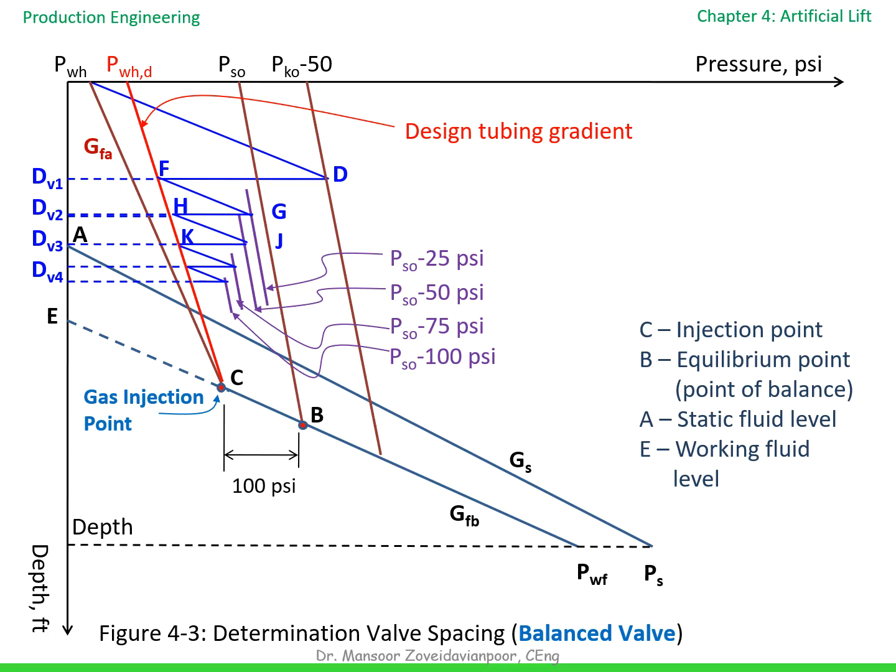If the spacing is poor, two valves may operate simultaneously or a valve may never close properly, resulting in inefficient unloading. A well-designed spacing pattern gives a smooth transition from DV1 to DV2 to DV3 to DV4, allowing the well to reach stable gas lift operation efficiently.